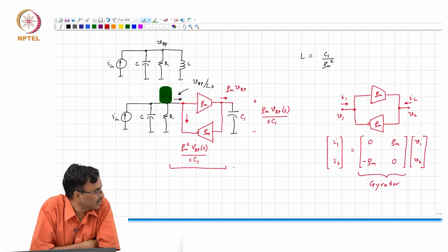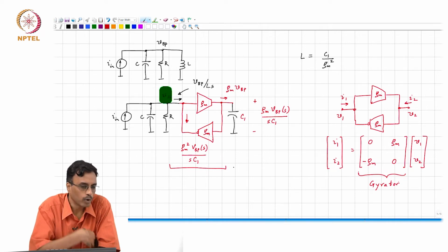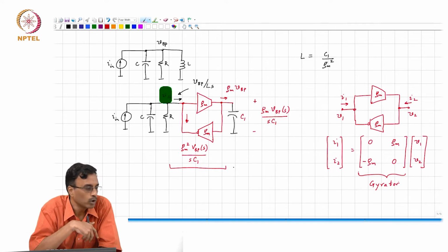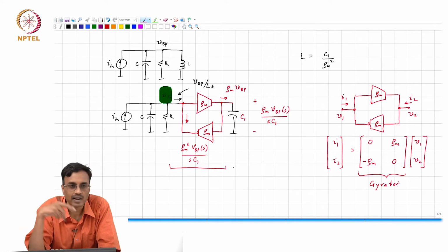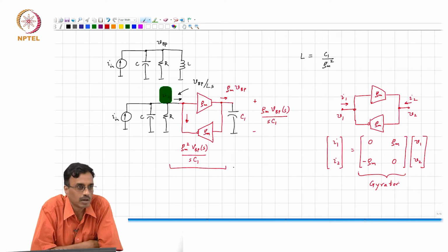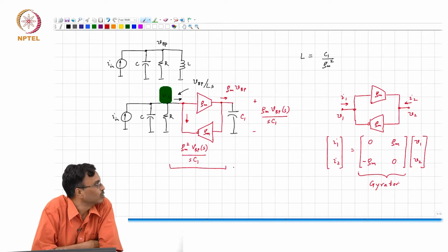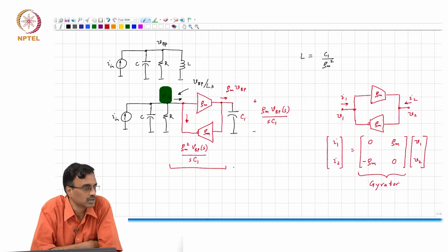And the gyrator basically is interchanging the roles of voltage and current at one port. Now, if you look at the other port, basically, port 1's voltage looks like port 2's current and vice versa. Okay, so within the appropriate scaling factors with the right dimensions.